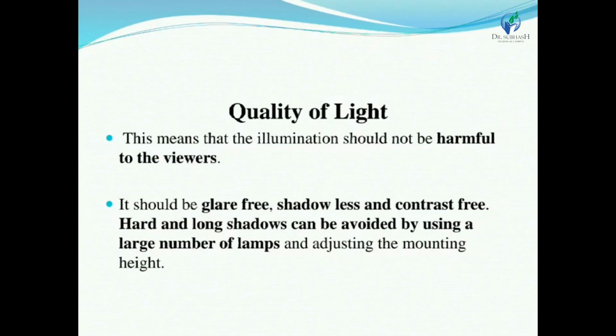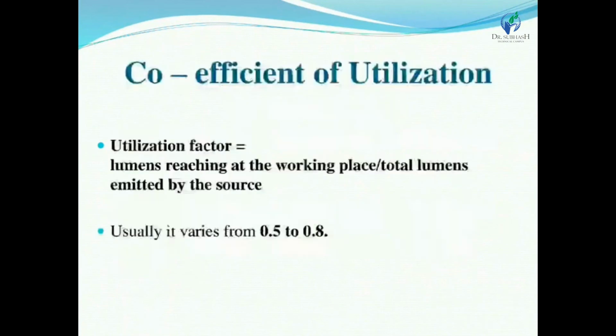What is the ideal light? So we are going to study quality of light. This means that the illumination should not be harmful to the viewers, harmful for his eyes, for his skin. Okay, it should be glare free, shadowless, and contrast free. Hard and long shadows can be avoided by using a large number of lamps and adjusting the mounting height.